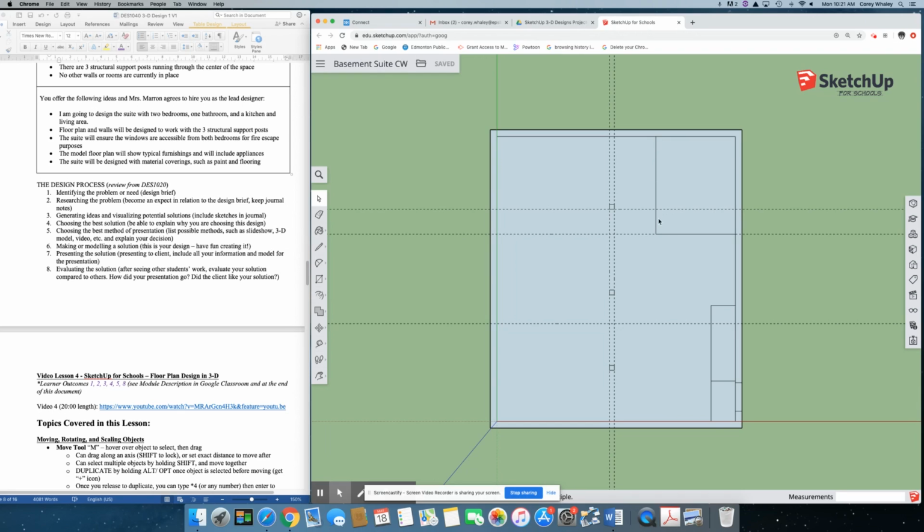So like this room that we created here, we actually will need to make a wall that's 4 inches, just to make sure that our specs are pretty much exact. So let's just grab our tape measure tool, and I just want to check a couple things. The first thing I want to check, I just kind of guessed at how far this distance was, but if I click here and then click over here, you can see the length in the bottom there. It's actually over 7 inches, so 7 inches and a quarter. So that's actually way thicker than a wall is going to be on the interior. And those teleposts, you could easily fit that into a 4-inch space.